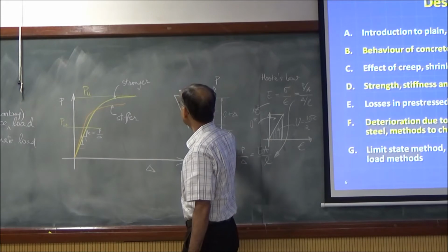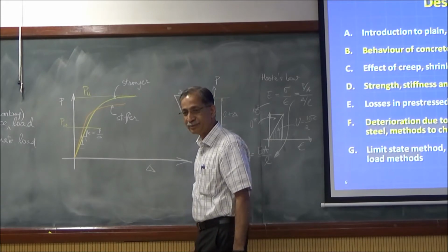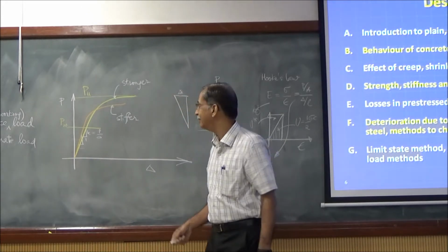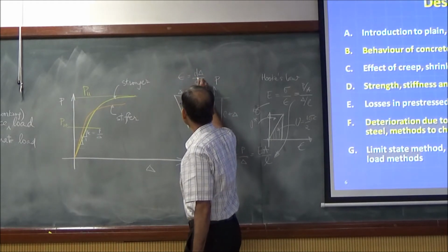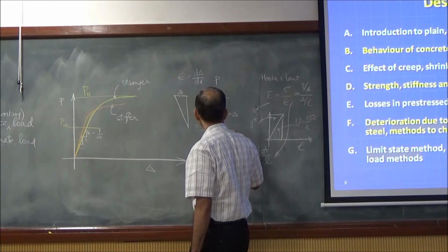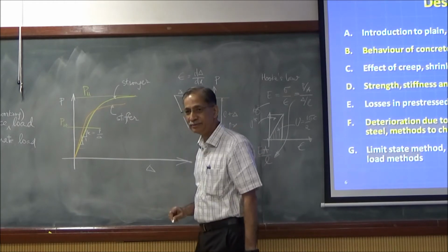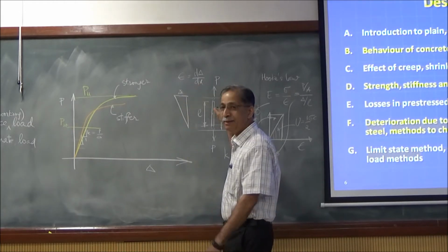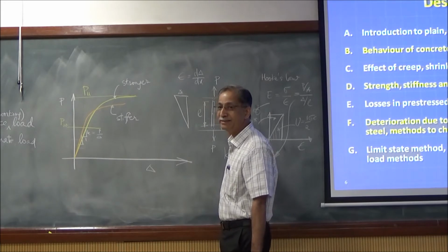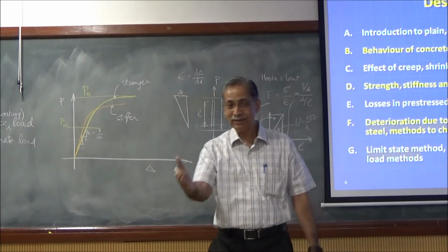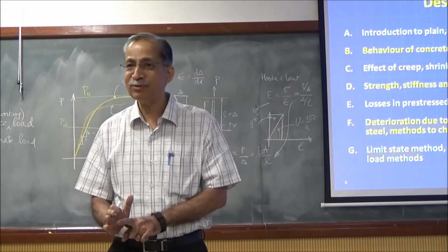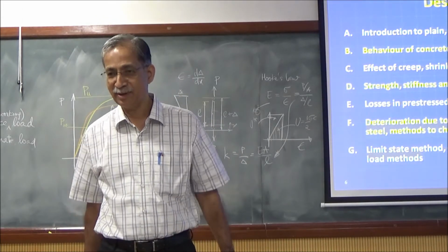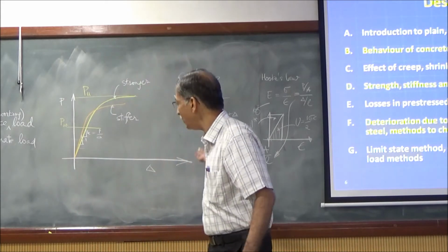Like this becomes your delta. So, strain in this case will be d delta by dx or whatever you want to do. So, don't get confused. If I hold it in the middle, then the displacement there is arrested. So, these are all important points. The displacement depends on boundary conditions, but the strain does not. Clear? This is all incidental.